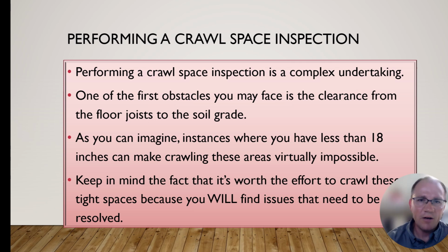But that's where you're going to find the major problems, especially as we're going to talk later about moisture issues. The closer the floor joists are to the soil, the more problems there can be. So I do understand if it's less than 18 inches, especially, it can be really tough to crawl. But you really want to get underneath there. It's going to be good for your business, good for the customer, and everybody's going to win.